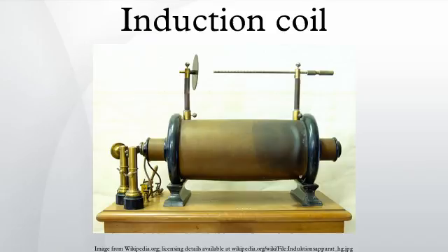The eddy currents, which flow in loops in the core perpendicular to the magnetic axis, are blocked by the layers of insulation. The ends of the insulated primary coil often protruded several inches from either end of the secondary coil, to prevent arcs from the secondary to the primary or the core. Mercury and electrolytic interrupters. Although modern induction coils used for educational purposes all used the vibrating arm hammer type interrupter